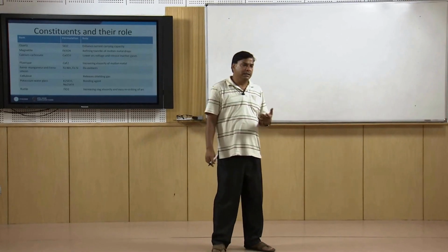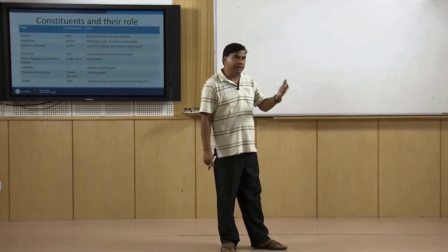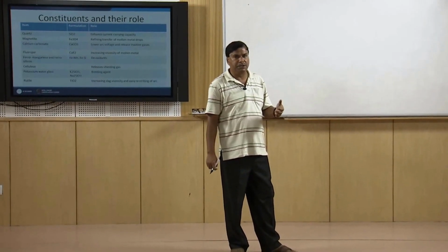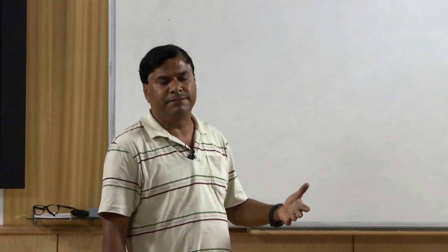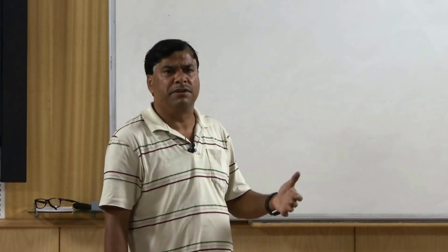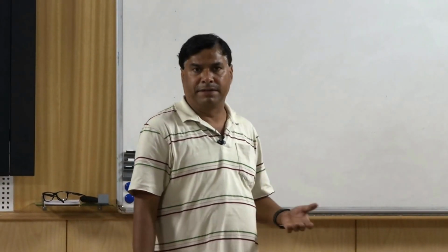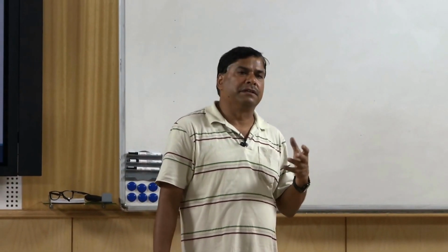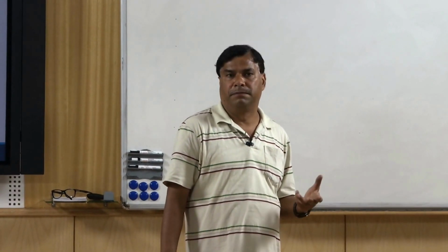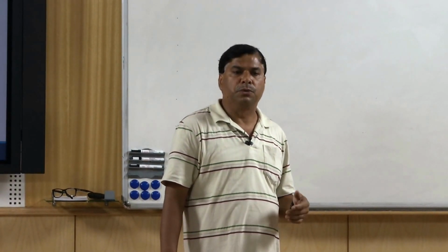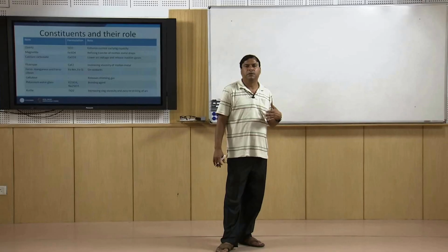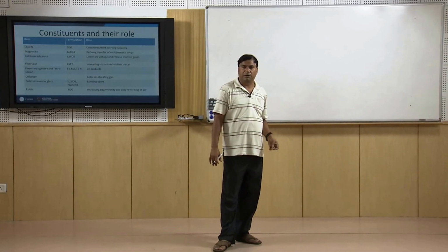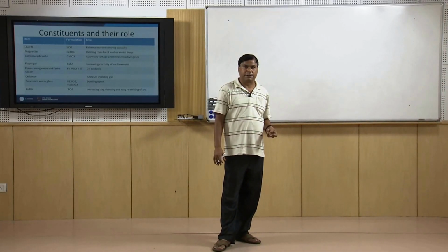And certainly the change in the amount of heat being generated will be affecting the solidification time and cooling rate experienced by the weld metal and heat affected zone, and these changes will in turn be affecting the structure and the mechanical properties of the weld joint. Those things we will look into in greater detail when we talk about the welding metallurgy related aspects.